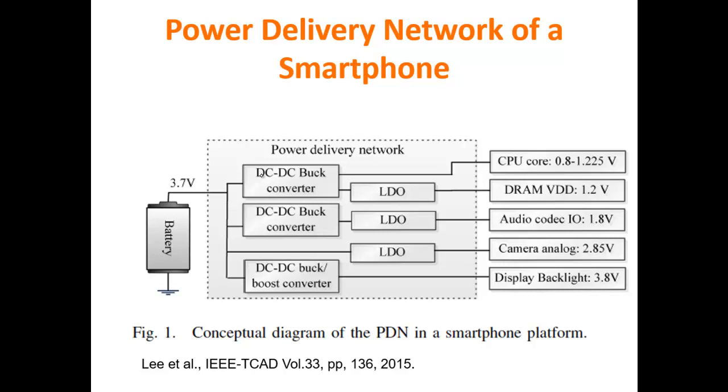In the DRAM, the main power consumption occurs when you dynamically refresh all the cells in the memory. Therefore, typically one can simplify things and use only one supply voltage, but with the particular requirement that this supply voltage needs to be very stable, very well fixed.